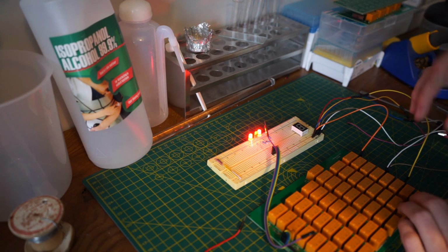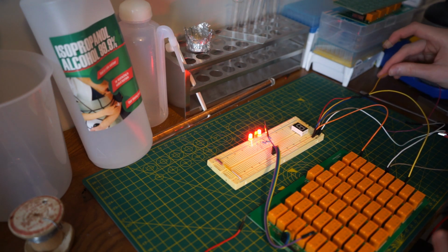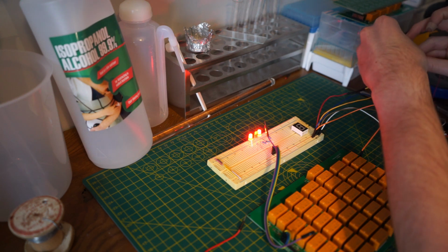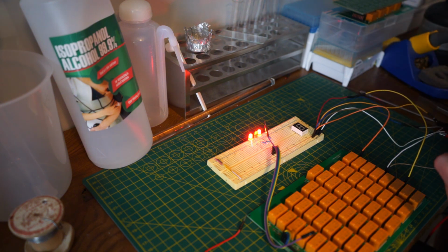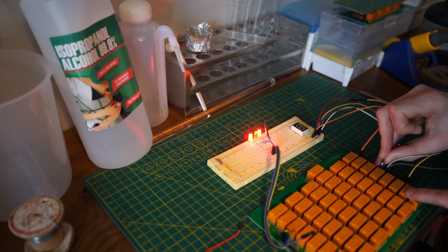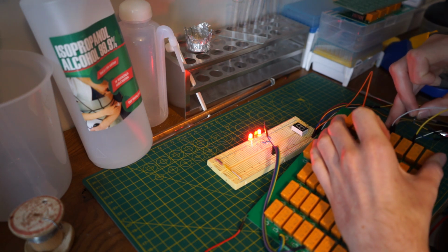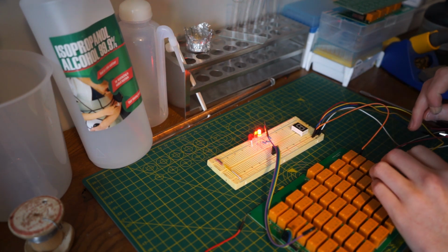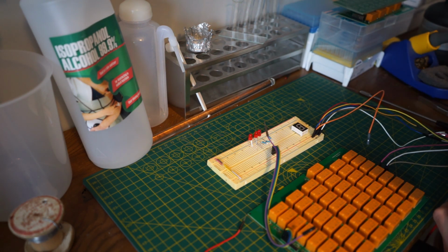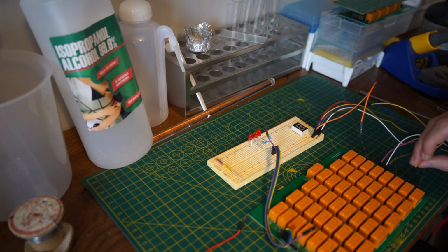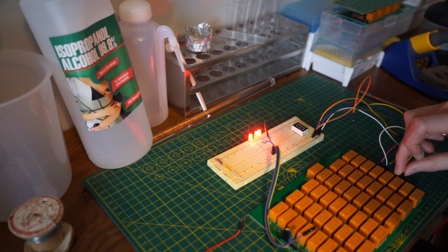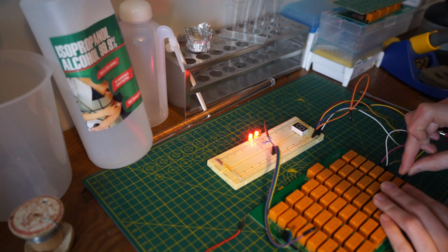We can now do the next one, which will be subtracting. So we take a positive lead, we attach that to the subtracting bit, which is down here. I don't know if you can see that, but one of these pins, you just put power to it, it changes it over to subtracting mode. So B will be 2's complement, so 1, that's 2's complement of 1, 2's complement of 2, 3, or 4 shall I say.